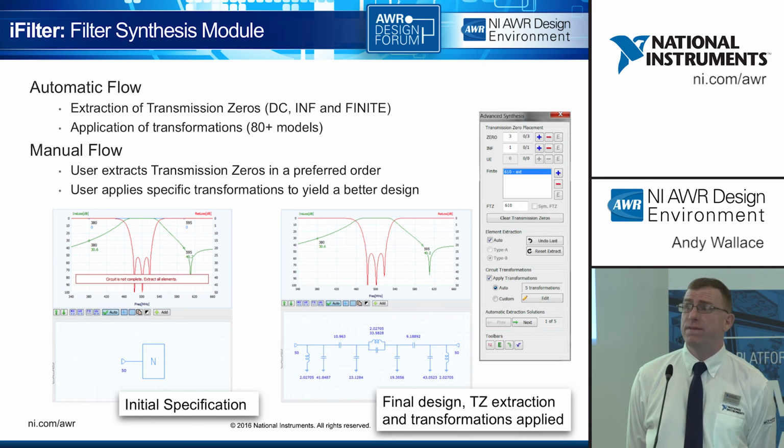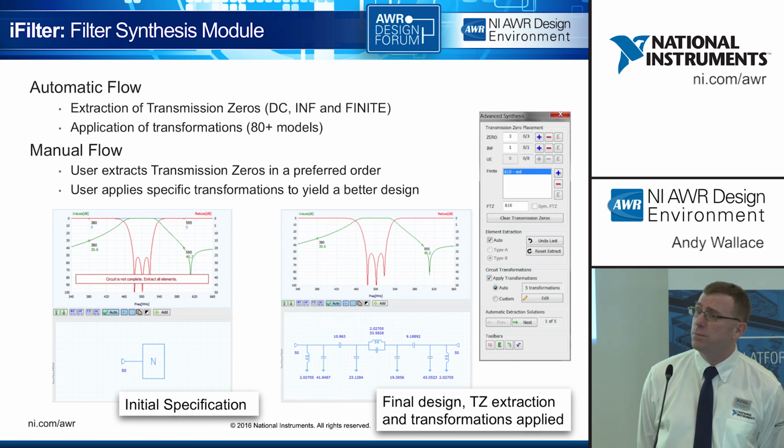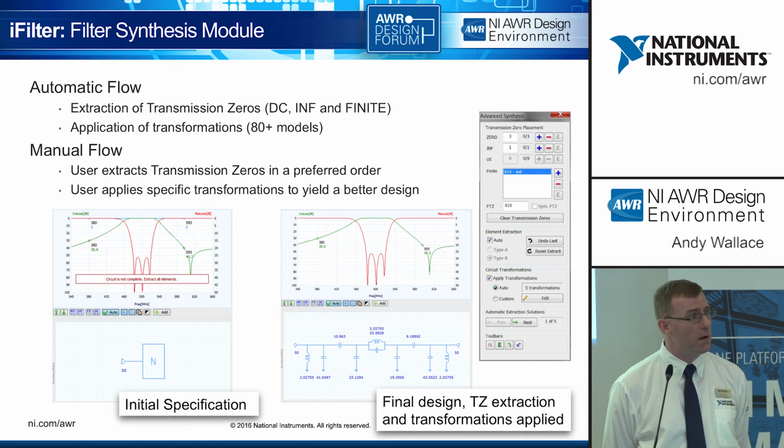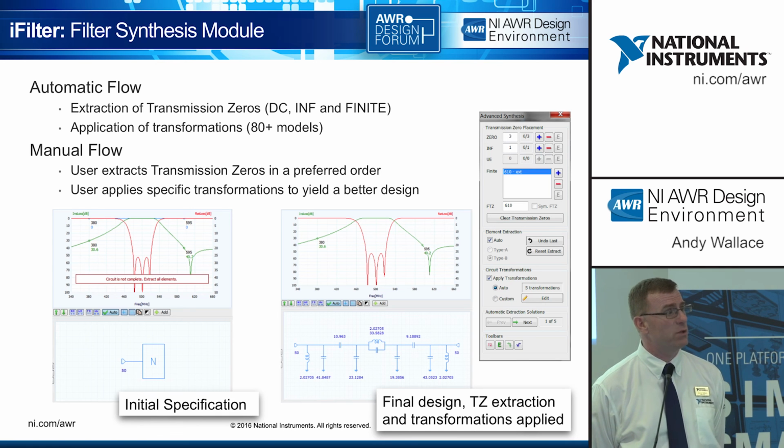What it is, is an ideal filter synthesis tool, so you'll end up with a lumped element equivalent. It can be planar too. And of course, the planar technology, if it were microstrip, would end up with a printed filter you could physically manufacture within a few moments.